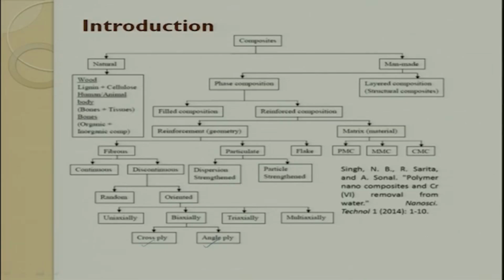So, you cannot tool also by using coolant. So, these are the challenges, whereas when you use natural fiber as a reinforcement, discontinuous, or say for example uniaxial or biaxial, if I use a jute mat, the abrasion action is going to be slightly less. When the fiber gets chopped off into small powdery chips, some of these chips can also act as lubricant during the process. So, the friction and the tool wear are to some extent suppressed when you use natural fiber reinforcement.